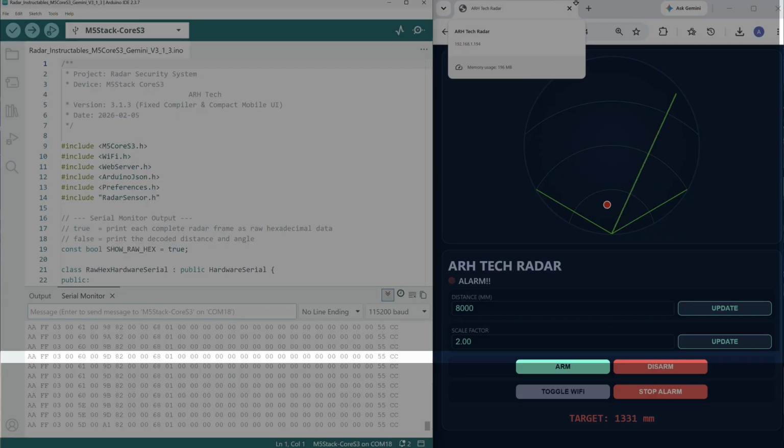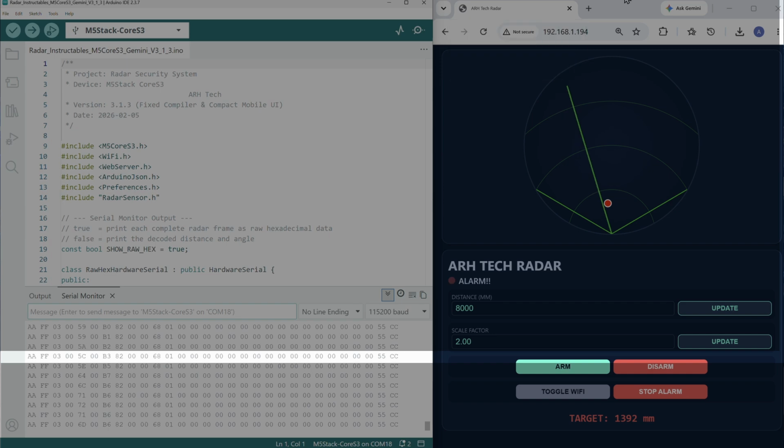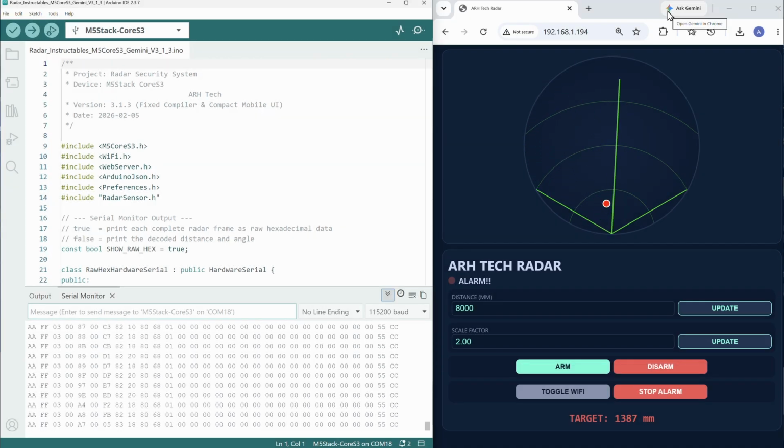The radar does not send ready-to-use values such as target distance or screen coordinates. It sends a structured stream of binary data, which is normally viewed as hexadecimal values. That data contains frame information, target records, position values, movement information, and other status data. Before any of it can be displayed, the software has to identify a complete data frame and decode each field correctly.